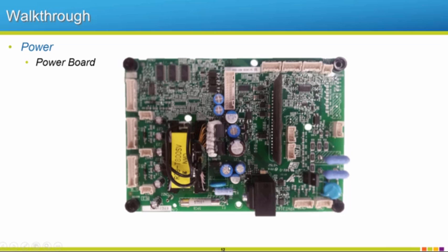And that's done through this transformer. It's just going to switch that high voltage to something usable to power that control board. These vary depending on the drive size. Some of our micro drives actually have all of these boards and the main circuit soldered, sandwiched together. So some of those smaller drives, if you're trying to repair them yourself, are not as useful to repair, but luckily they're pretty cheap, so you might as well just toss it and grab a new one anyways.